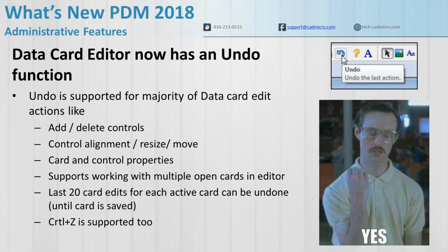This is a big one. This is a huge one. For those of you who administer PDM, there is now an undo button in the data card editor. Big bone of contention for people who do this kind of work. There's really not much more to say. It works just like any other undo button. Just one thing to note, that it goes as far back as 20 data card edits, obviously pre-save. If you do a save, then you lose any sort of undos before that save, just like any other undo button.